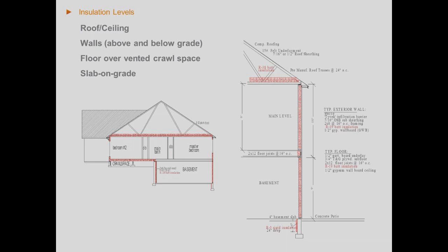Insulation levels, so this case study is giving them to you for the roofs, the walls, the floor, and the slab. Those are my building thermal envelope components. And I go out and I'm going to enter those into the software for whatever it might be, cavity and/or continuous.